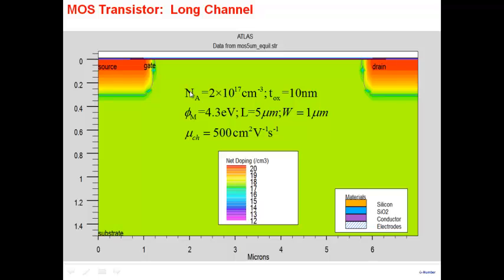And these are the results I will use from simulation. So this is the MOSFET structure, and some of the results that I'll show you pertain to this particular structure here. You can see we have source and drain here, and the substrate is here. The doping in the substrate is uniform, 2 times 10^17. The thickness of the oxide is 10 nanometer.